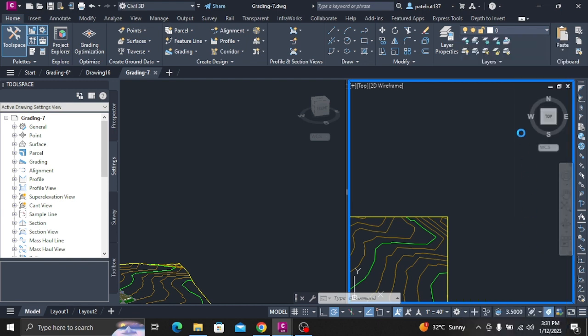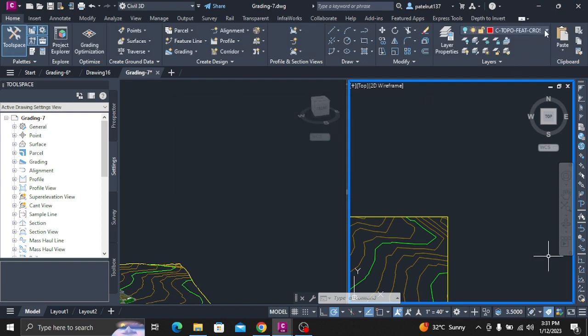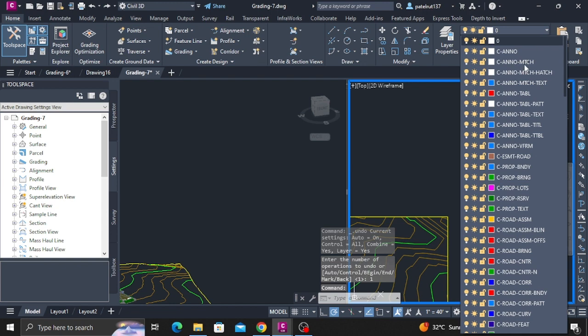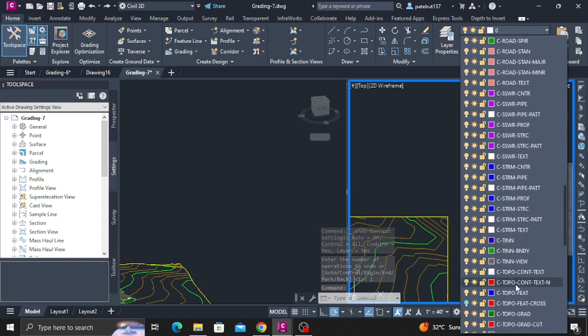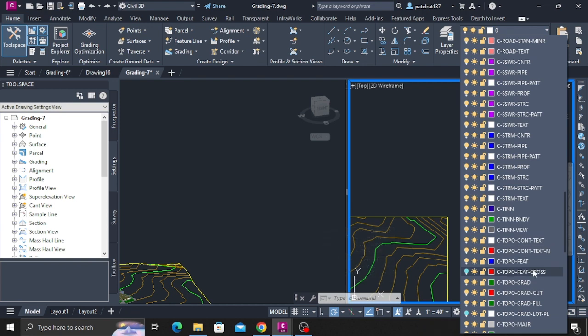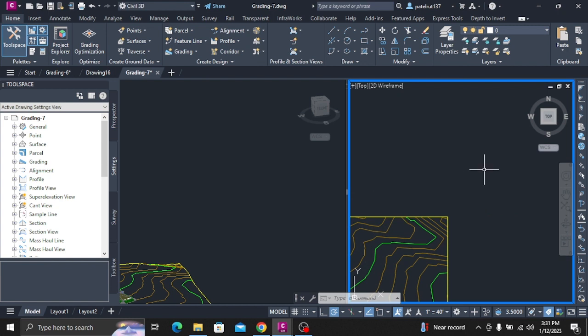You may flatten either the entire feature line or a selection of points. In the row, in the elevation column, change the elevation value to 402.00 foot. In the Grading Elevation Editor, click Select a feature line, parcel line, or survey figure. In the drawing window, click the building pad feature line. The elevation points of the building pad are now displayed in the Grading Elevation Editor.